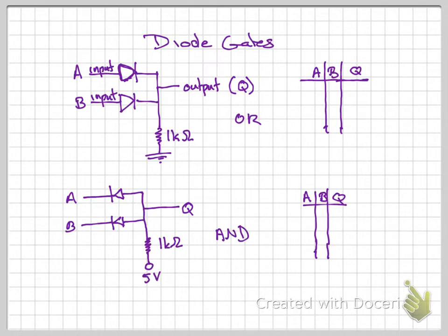So imagine that we put a 5-volt input. We're just going to pretend that these are actual digital gates, so it's going to be a 0-volt or 5-volt input. And let's just think of either CMOS or TTL, that somewhere between 3 and 5 volts is high, and somewhere between 0 and 1 volt is low, but between 1 and 3 volts is indeterminate.